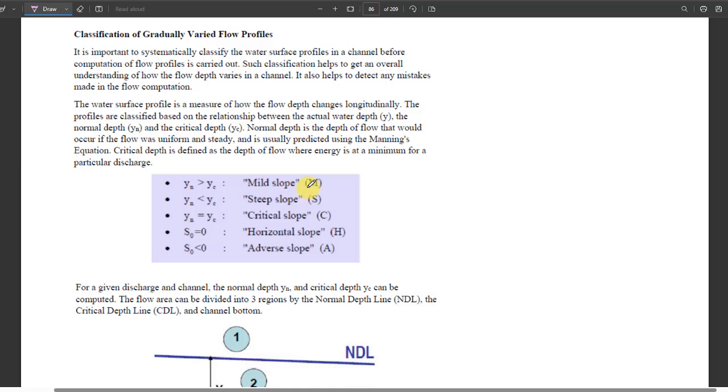Therefore, the change between, for example, a slope that is subcritical and then another slope that is also subcritical, but maybe more mild or less mild. What about mild? Mild represents subcritical, so it's the same meaning. Steep means supercritical. But it is related to slope, okay?